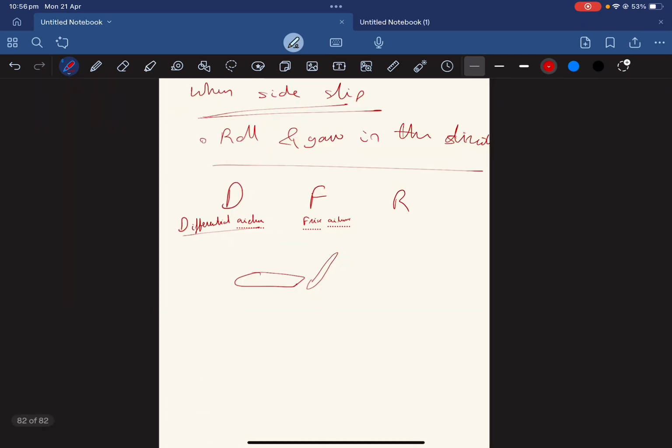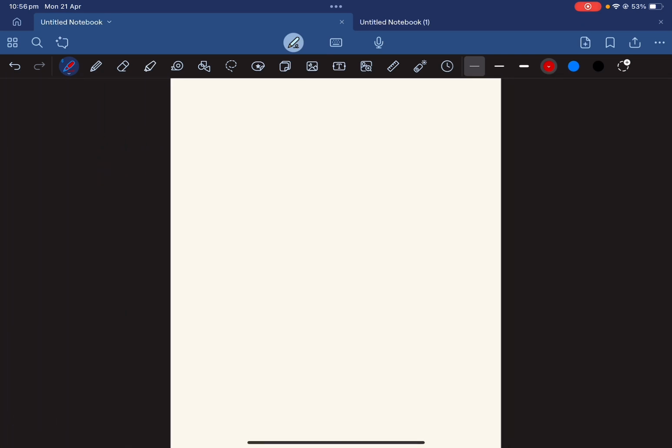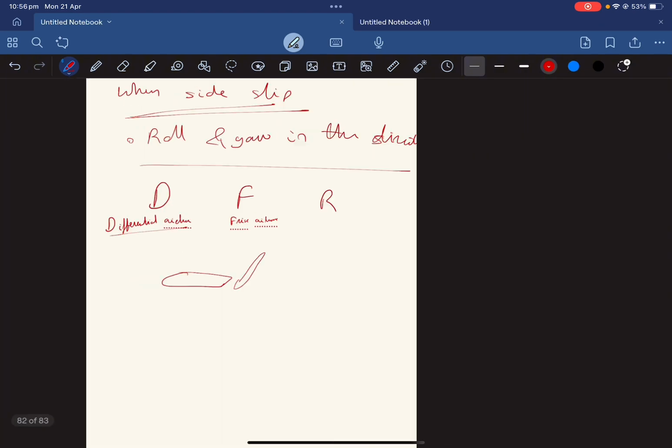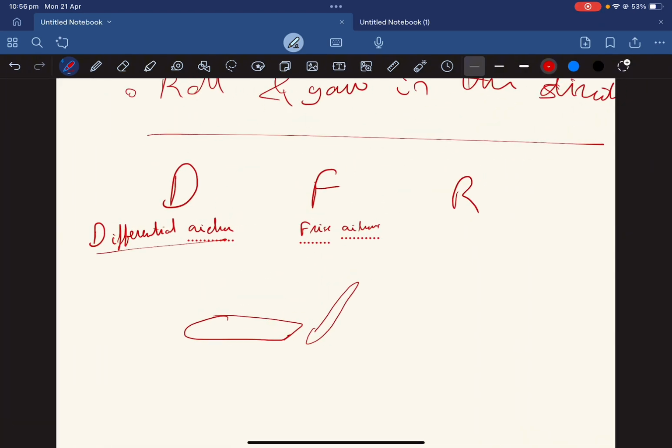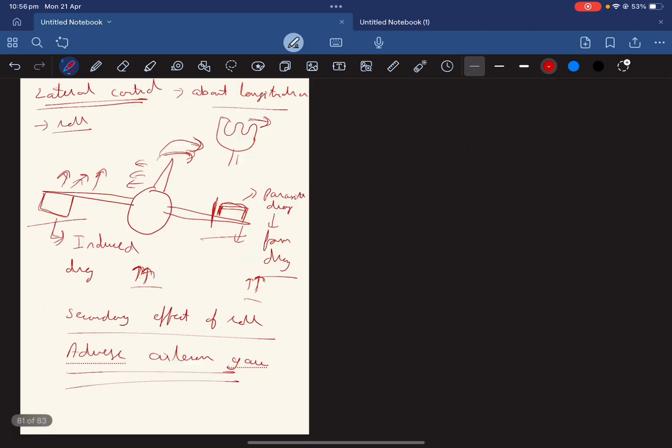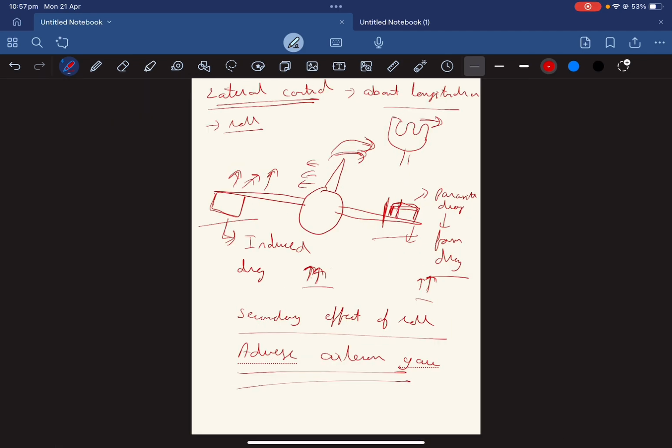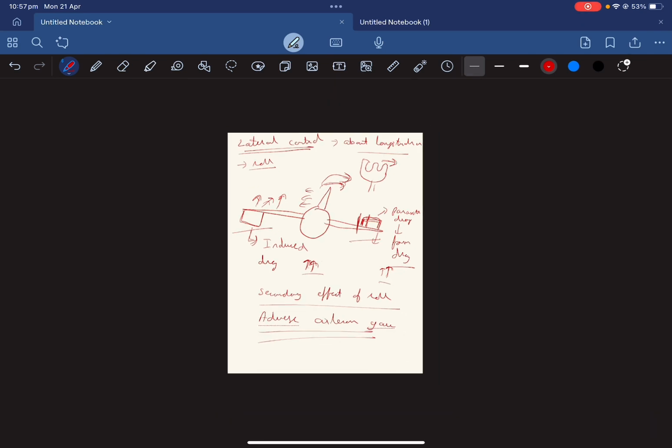What we do is, the leading edge of the upgoing aileron, we make sure that some of it is projecting into the wind. Like it's coming out of the frame and into the air. So what we want to do is increase the parasite drag by this, right? Again, if you're increasing drag over here, then you're going to make it equal, and in a way, you're solving your issue.